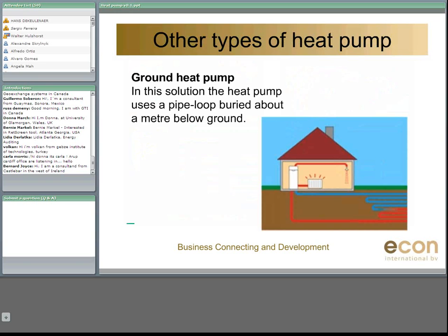If you look at the different types of heat pumps, I've spoken about the air source heat pump, which is collecting heat from the air outside and transferring the heat to your home. There are also other types of heat pumps, which I will show you in the following slides. The most important aspects to consider during the evaluation of the different types of heat sources are the availability, the temperature level of your house, and also your annual temperature fluctuation outside. And I think also the investment costs are very important when you consider a type.